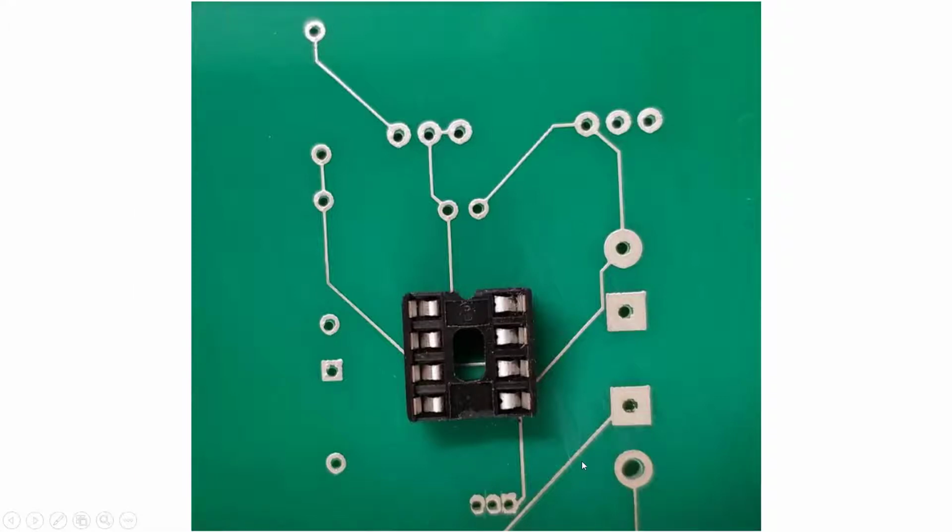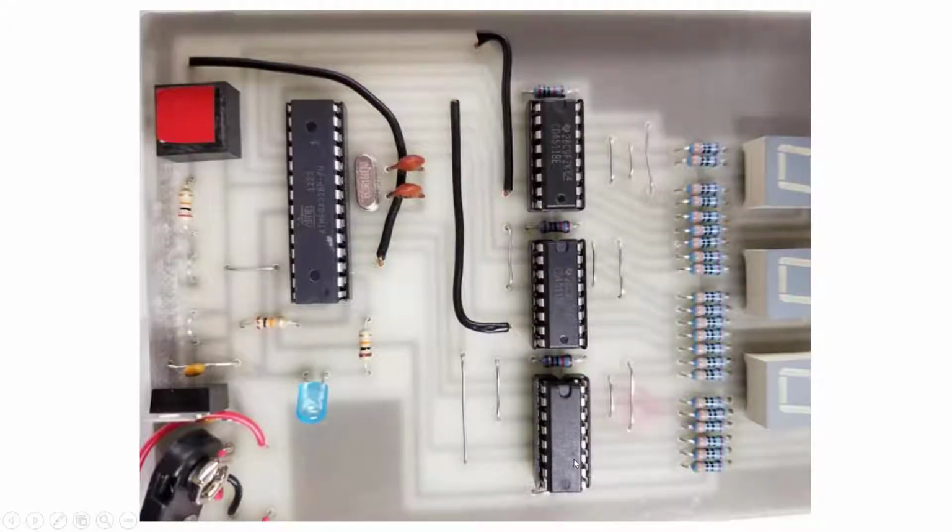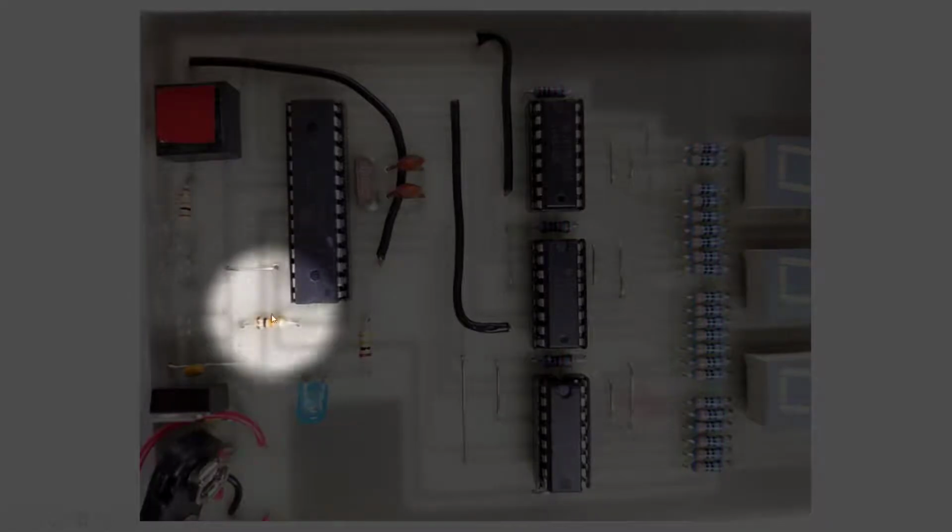A via is used in cases like this. This is an old printed circuit board made by hand that I did. And you notice how sometimes there are so many copper traces on one side of the board that you can't run across them because that would connect runs you don't want to connect. For an example like this, I needed a wire to go from this trace, you can see through the transparent board, to the other side where the copper run is, to connect to this trace.